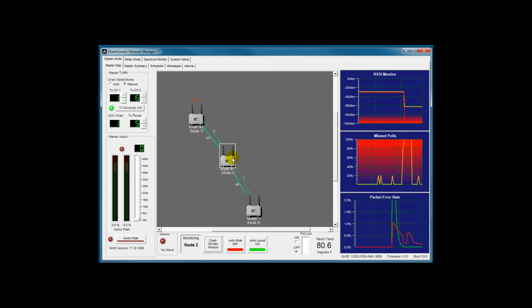So that's how you turn an intermediate node into a repeater, listening on channel 1 and 6, transmitting on 2 and 7, etc. So you can have a main backbone of these repeater nodes talking to a group of remote nodes by doing just what we did.